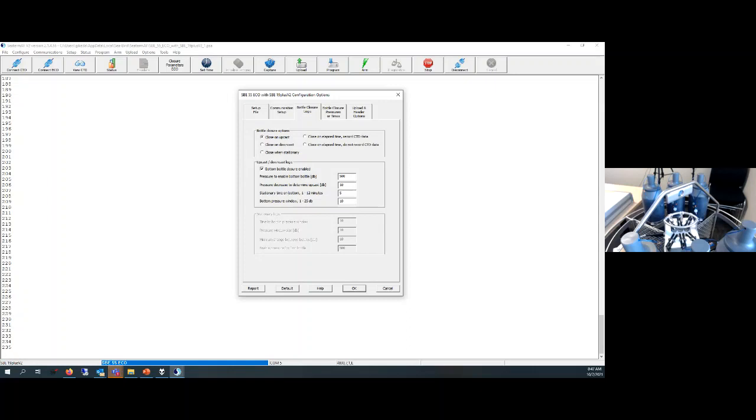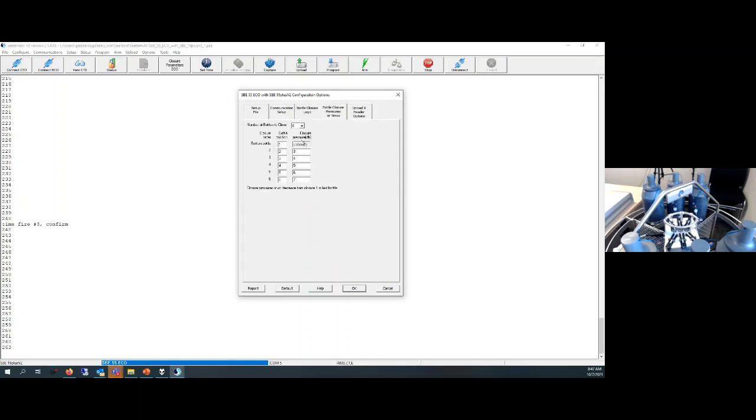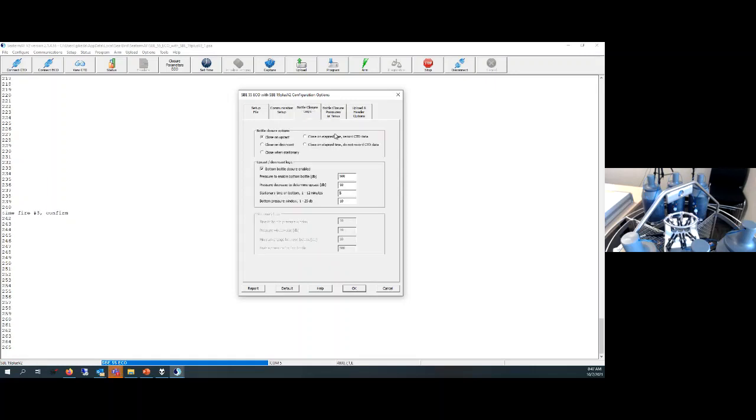Now, you might be in an environment where you have significant amounts of ship heave, and so stationary is relative to the motion of your vessel. In this case, we want to define a window of what is quote unquote stationary. So in this case, I've defined 10 decibars. After we meet this minimum pressure, as long as my CTD package is sitting here within a 10 decibar window for 5 minutes, it's going to close bottle number 1, the stationary logic.